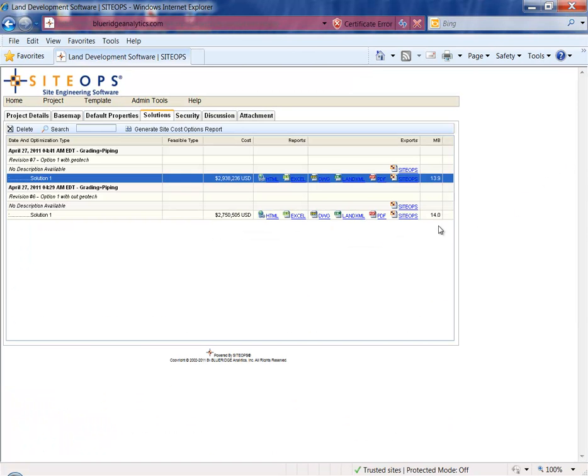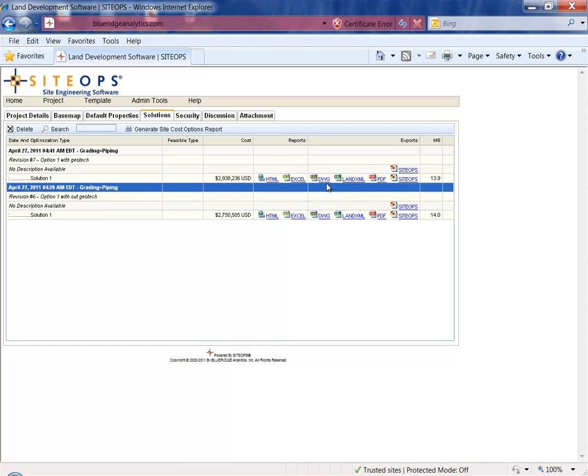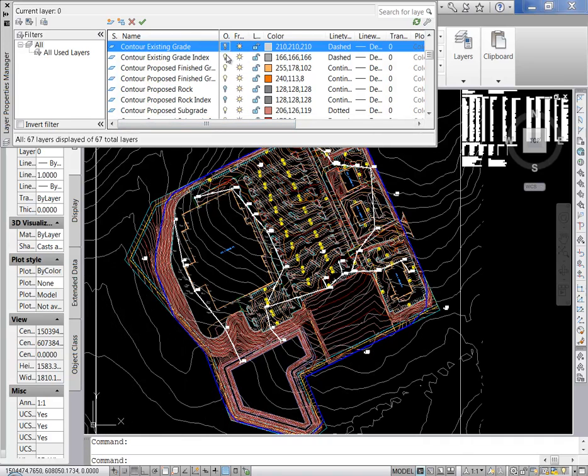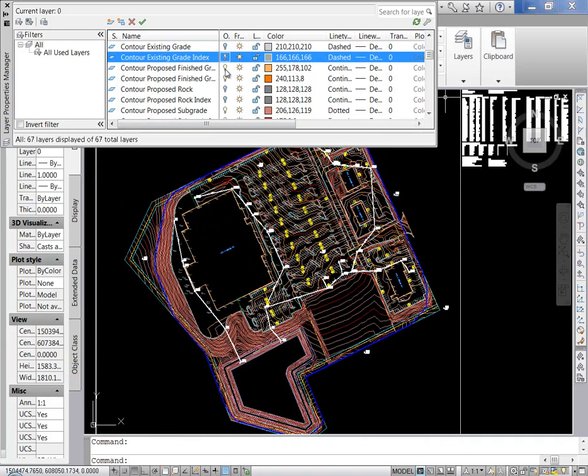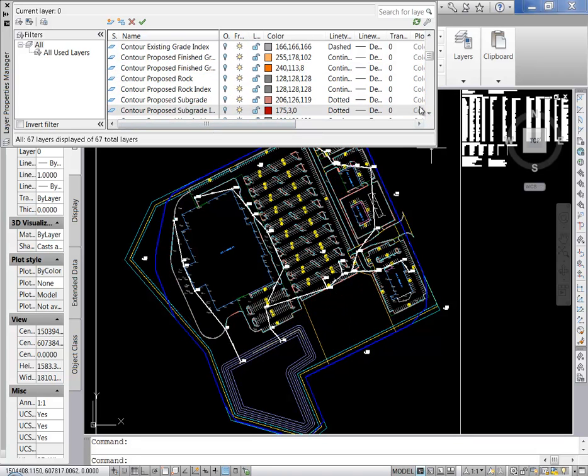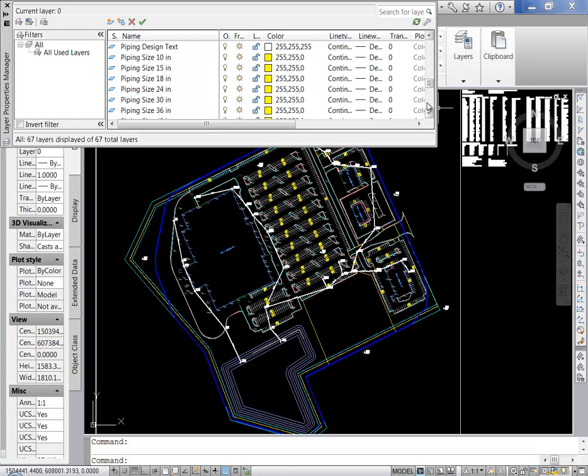Now we also bring this in for an output as an Excel, but you also have DWG and LandXML files that you would take the design that you want to go forward with to construction document phase. For example, pick the DWG, open it up inside of Civil 3D. We'll turn off a few layers. Now we give you finished grade and finished subgrade contours because we do grade the subgrade, because you can put those material thicknesses in there. We also give you 3-line curb sections. We give you all the information you need to pick this up and go forward in your design.